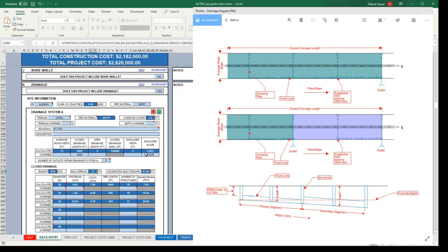This is also taking into account a crown section. So it's really the area divided by this, divided by 2 to account for a crown centerline section. So we can play around. If I change this from New York 123 and go back to Main Street, where we have maybe a greater max spread width, you'll see that now we can go 300 feet, which makes sense because we are allowed a greater puddle spread.